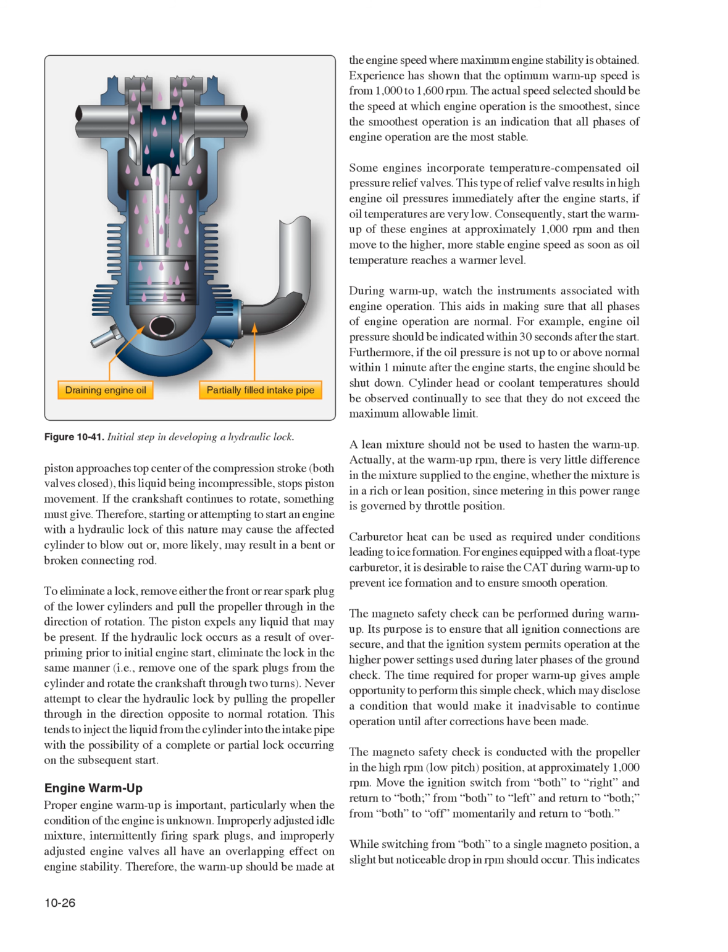Some engines incorporate temperature-compensated oil pressure relief valves. This type of relief valve results in high engine oil pressures immediately after the engine starts, if oil temperatures are very low. Consequently, start the warm-up of these engines at approximately 1000 revolutions per minute and then move to the higher, more stable engine speed as soon as oil temperature reaches a warmer level.